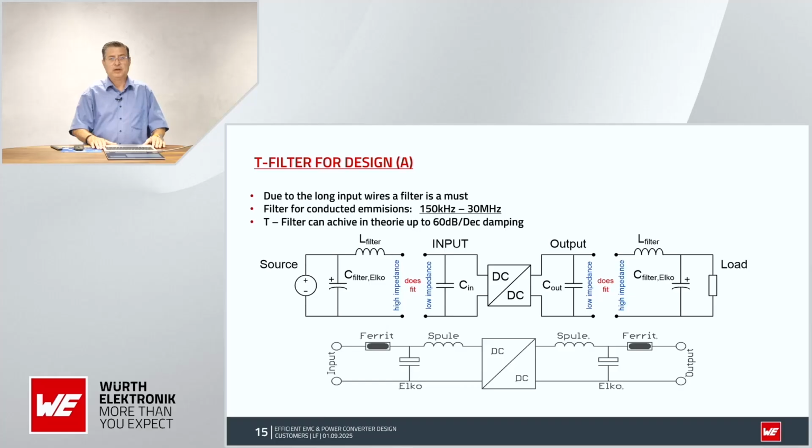So what do we have to do now for the DC-DC converter? First of all, we will have two stages. We will have one in buck mode filtering, and we need to filter the boost mode as well. In boost mode, the noise is not on the input but on the output. In buck mode, you don't need to focus on the output; you have to focus on the input. The input will be the noisiest area, and in boost mode the output will be the noisiest area. So actually we need an input and an output filter.